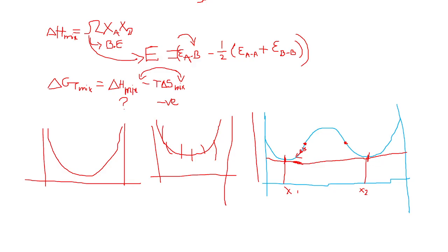You will form nuclei because of this undercooling, you will have nucleation, and if the T2 temperature is appropriate, you will also have the diffusion. Just like I have said before, if the temperature is too low, for example, if you are trying to undercool it very fast, that means the undercooling is quite high. That means you can easily form a nucleation, right? The nucleation rate will be higher.